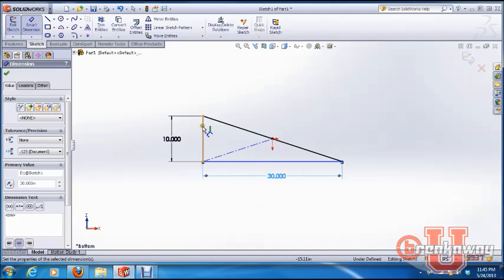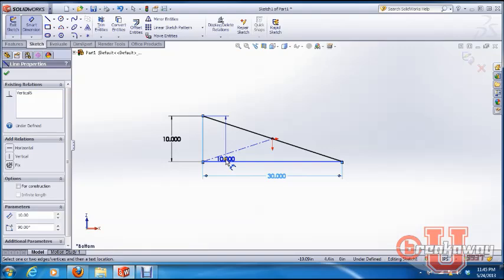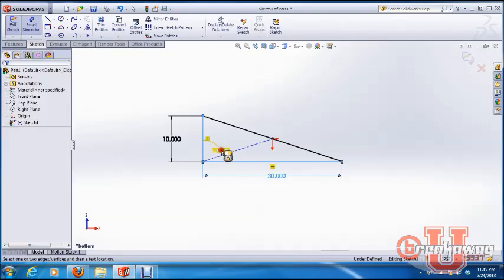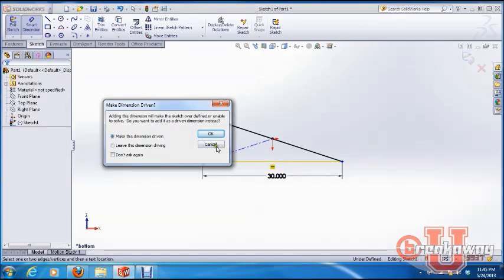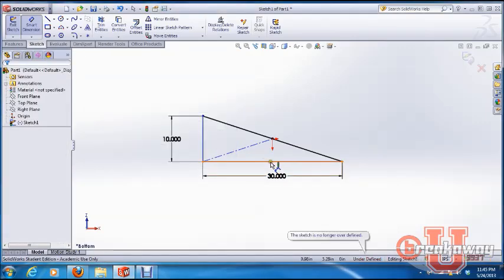Now, I'm pretty sure since I cut the top part out, this is still coincident. So remember, like we were talking about with our geometry lesson, this is just a side and a side. So we want to make sure that this triangle doesn't like to mosey on us. So I just did smart dimensions again, selected this leg and this leg. Nope, they did keep it. Very good. So I kept those relations as well.